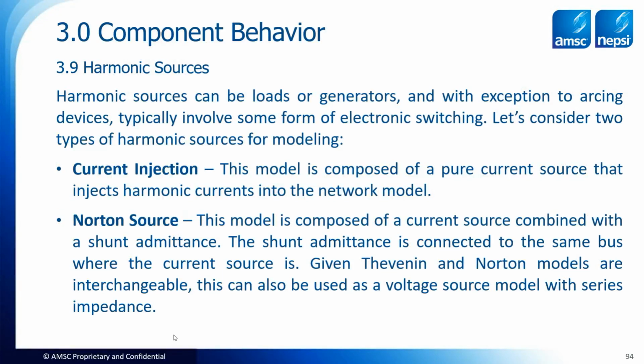That way, when you've completed your harmonic analysis, you can have a clean paper trail, and in your report or your memo, whatever you're going to write up, you can say, this analysis was performed, these are the results, and my data for the spectral current injections originated from ABC manufacturer, and here are those numbers, and document them in your analysis.